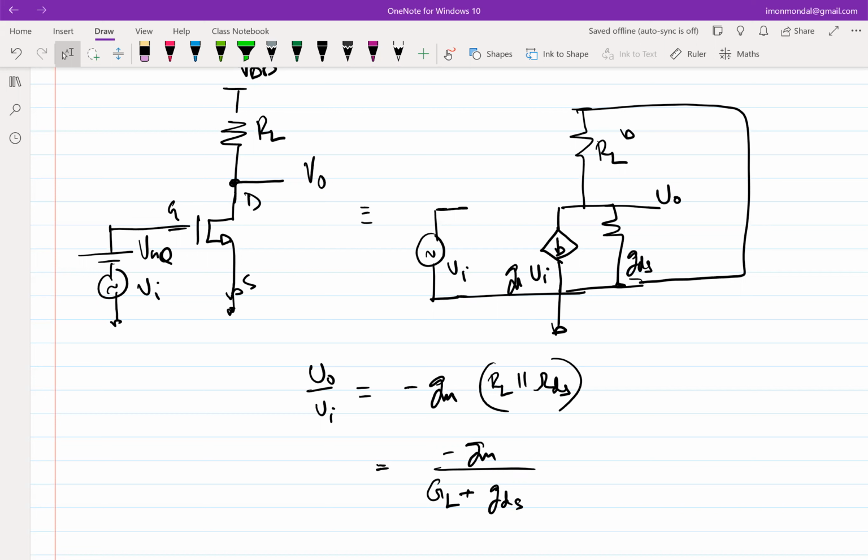But now can I get that? What is this model telling us? It is limited by the transistor's own characteristics. So there is a maximum gain that you can get out of a real transistor. You cannot get infinity. Just because you have loaded the output with an infinite resistance doesn't mean that you'll get an infinite gain. Even theoretically, you will not get an infinite gain. Okay. So how much gain you will get? What is the maximum gain that you can get now?